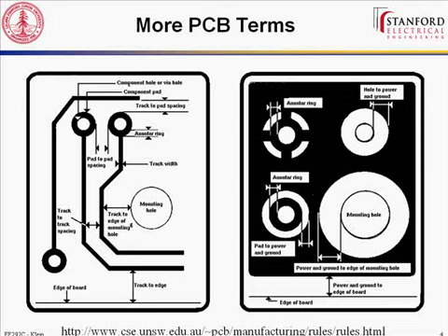Why would you want to put something into the via? I mean, there would be paths to... So the question is, why would you want to put something in a via? And you don't, unless you're debugging a board. But you will need to put stuff in component holes if you have through-hole components.